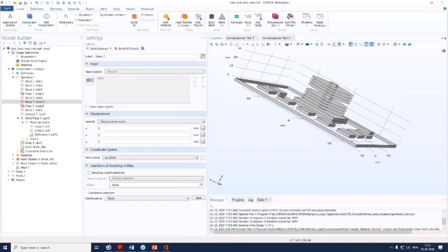So if you have such an absolute tolerance for a geometry which is located really very far from the origin, in that case, your absolute tolerance will work in such a way that your entire geometry may also get removed from your geometry sequence. Hope that answers your question.